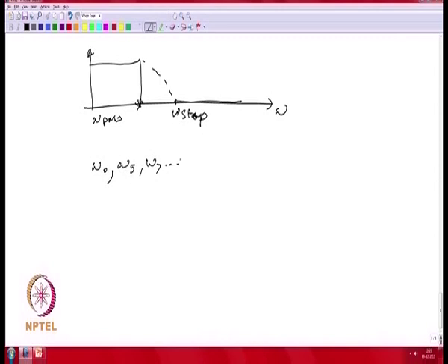Your harmonic frequencies in your pass band, especially if you are trying to build an active filter which is trying to inject and control the harmonics in an accurate manner. You might also say, for example, try to reject the harmonics that the grid is putting on your power converter by actively ensuring that your bandwidth includes your harmonic frequencies. So, your pass band needn't just be your fundamental frequency, it can actually extend further out depending on your bandwidth targets of your power converter.